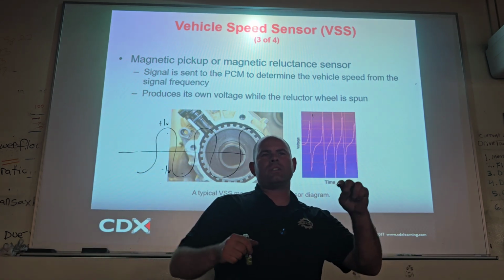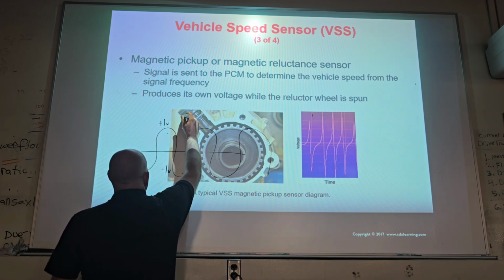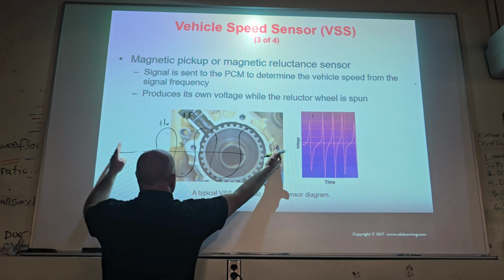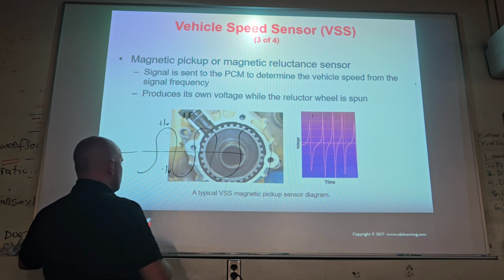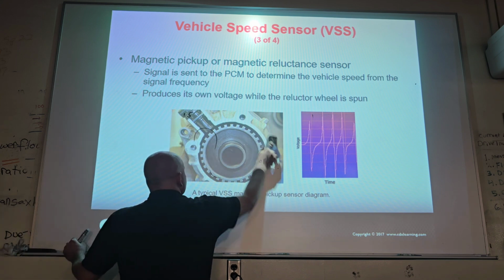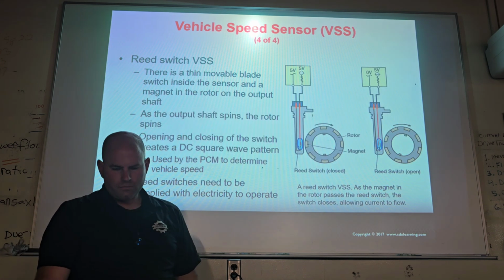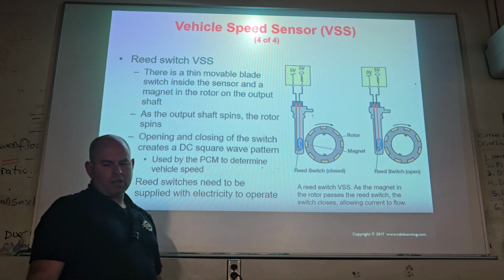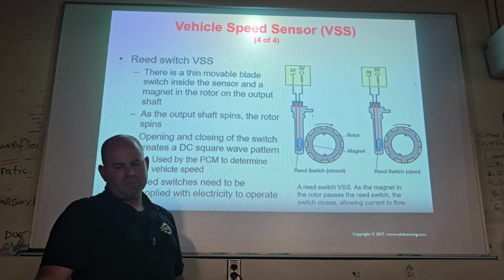So just 2 wires. The faster you spin, the more it'll be. You might get like to maybe 1.5. But you'll also get these closer together because it's up and down faster. Right, so that would be your basic magnetic pickup type speed sensor. Cool. And then this is a little more similar to a Hall effect type switch.